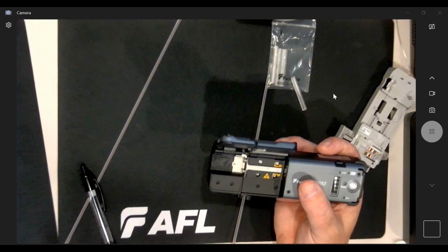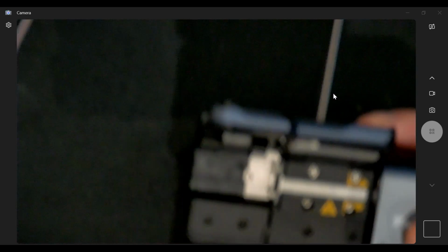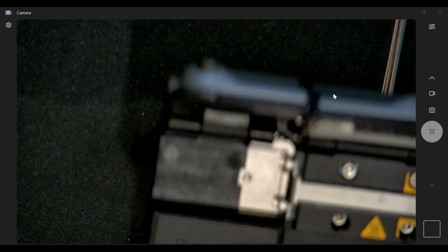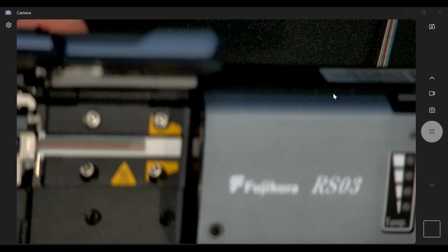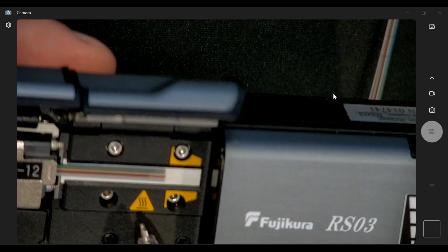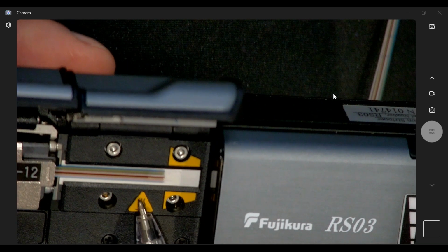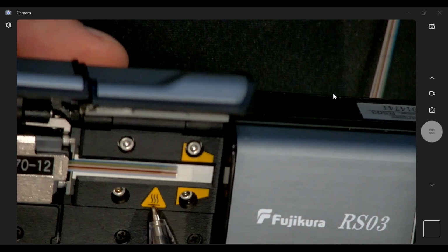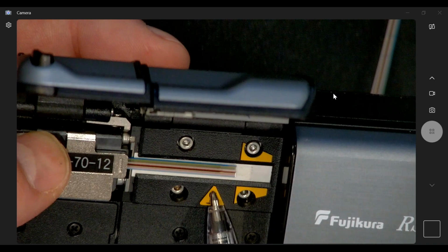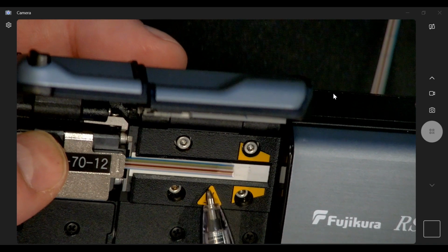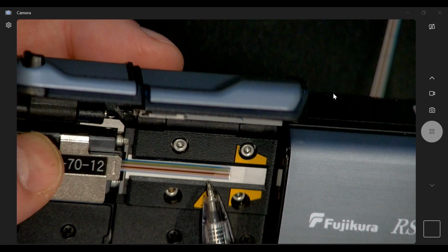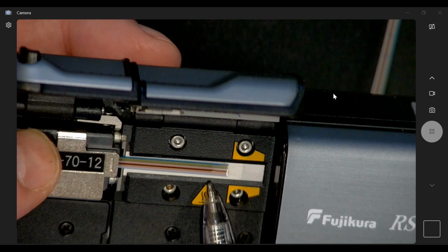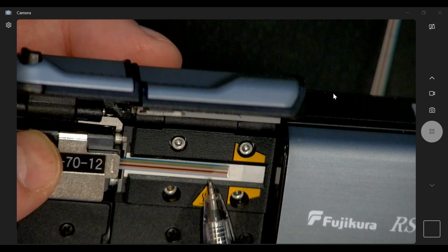So I'm going to take that fiber holder I just removed, and I wanted to point out something on the fiber holder. As I load this ribbon into the fiber holder, the blue dots closest is this point here. If you look at your hot jacket stripper, you'll see this little triangle heater insignia. This represents the shortest possible length of the ribbon as you attempt to strip that material off.